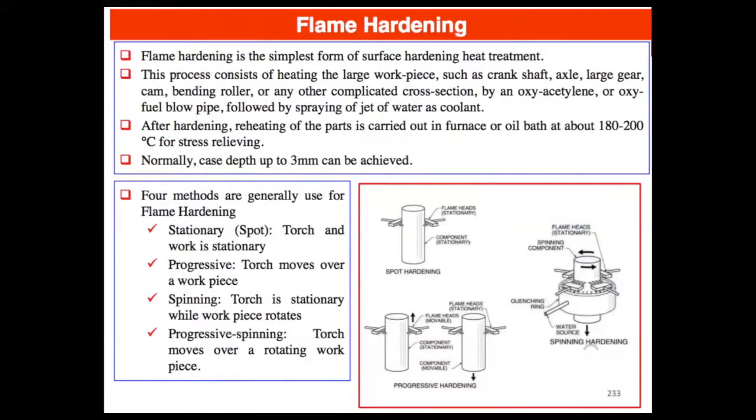For flame hardening, essentially yes, this is the simplest form. You're just heating up the surface locally. You're not heating the entire cross section of the part, right?